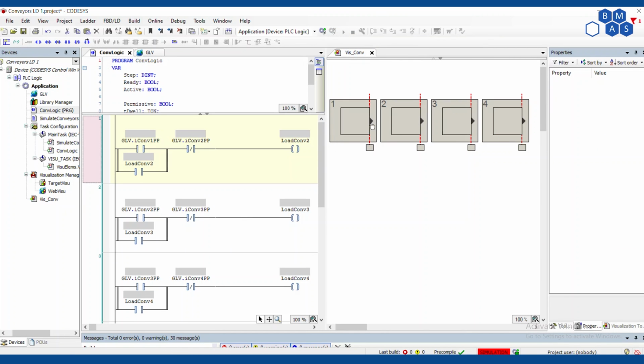Conveyors are often treated as an individual thing from a programming standpoint. So we're not looking at this usually as a whole system and trying to make an overarching program that considers that whole system at the same time. We usually make a program that considers one station at a time. And then those are like a bunch of little programs, if you want to think of it that way, inside of a bigger program.